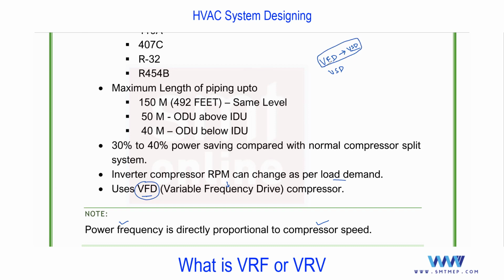I'll give you more points related to it. But first of all, you see, if the system is only VSD, it means it can change the speed without changing the power consumption, by changing the speed using gears or pulleys, but the motor speed is going to be the same. The motor speed is not changing. We are changing the fan speed by changing the size of the pulley or using gears. In that case, the system is only VSD. There is no change in the power consumption.